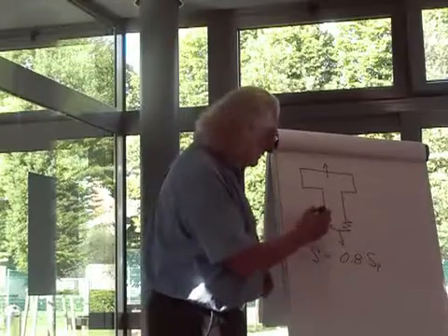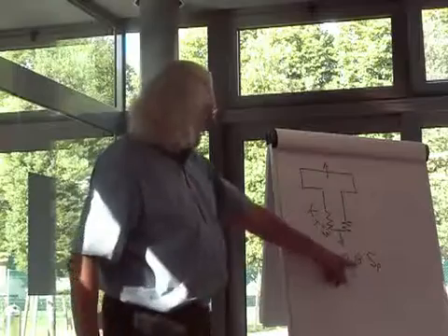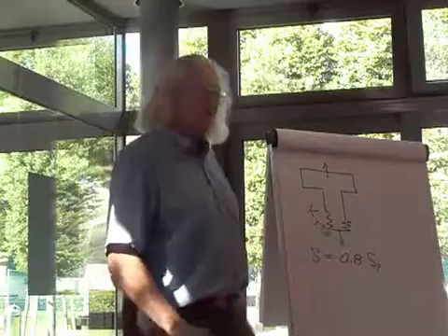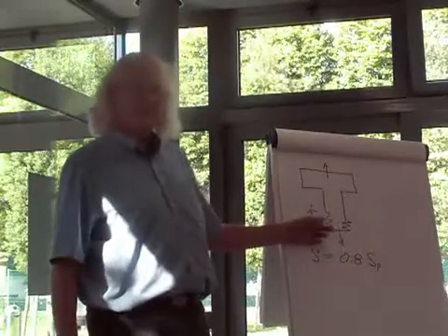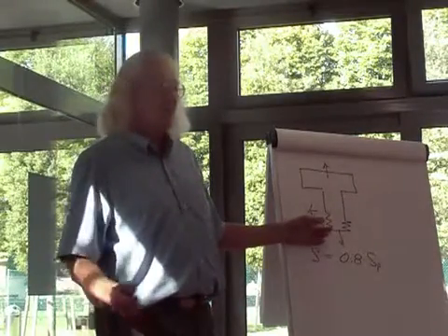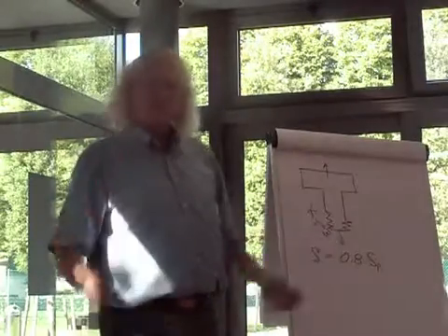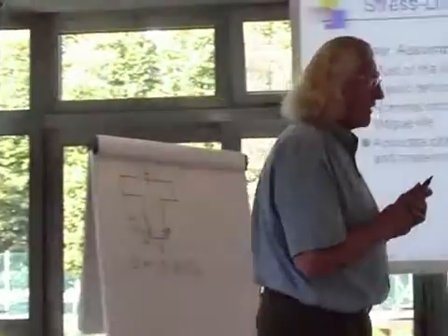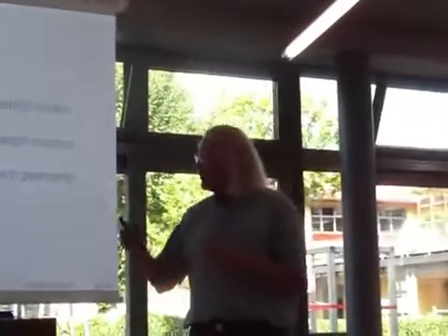Yeah, 3, right? But look, if the stress concentration factor here is equal to 3, and I'm already at 80% of the proof strength, I'm now at 2.5 times the strength. So the stresses in here are 2.5 times the strength of the bolt. So obviously they're all broken. Or maybe I should never preload things. But I can assure you my new Lamborghini, or Ferrari, it doesn't matter, will not work unless I preload everything, and certainly the airplane wouldn't work.